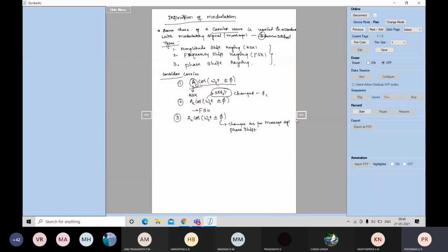And when you assign for 00 a phase angle of 0, for 01 pi by 4, and for 10 and 11, because when you go by bits, dual bits combine to form symbols, 4 symbols are possible: 00, 01, 10, 11. When this is with 0 degrees, this with pi by 4, this with 3 pi by 4, and this with pi by 2, then such phase angles, when you are changing, it is directly equal to PSK.